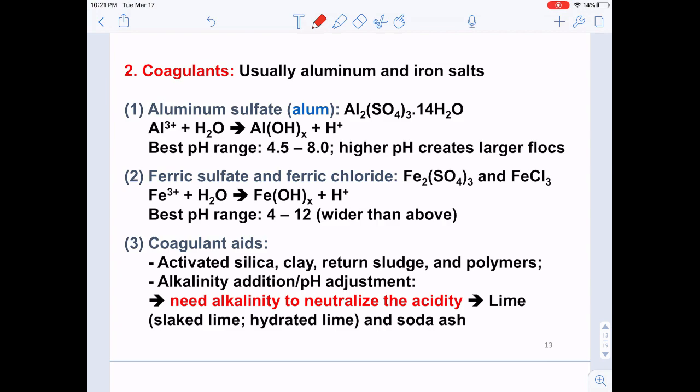So in terms of the coagulation, again, this is trying to quickly review the contents we learned, right? So we want to put in the polyvalent or trivalent ions. We can put in the aluminum sulfate, right? So aluminum is a trivalent ion. So based on this equation here, you can see that once we put in the aluminum ion into the water, it basically generates these hydrogen ions. So if I ask, what is going to happen if we put in these coagulants in the water in terms of the pH? So the pH is going to reduce, right? Simply because we generate these hydrogen ions from the water.